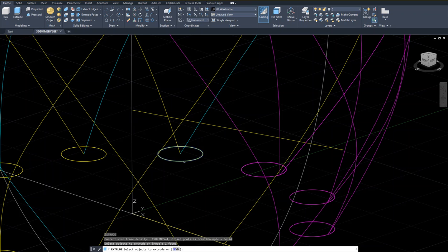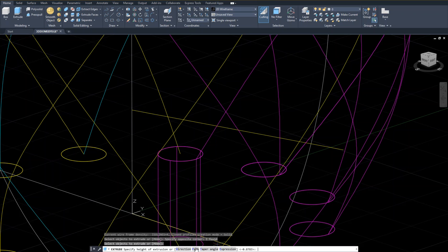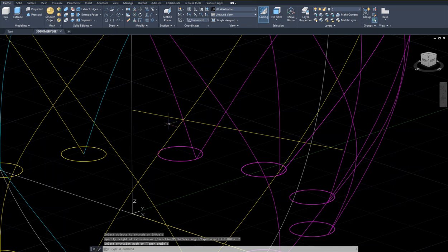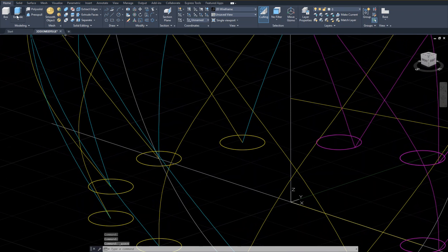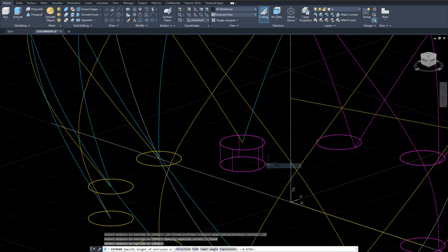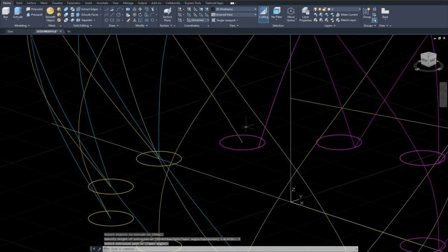Extrude is back. Now you hit enter key, enter, and then go over, select the path option. Okay. And perfect. Enter. And select the circle, enter, select the path option. Okay. Good. And Control S from time to time. Control S for save. We're going with the extrude option again. Okay. And select the circle, enter. Now we need to select the path option. Okay. Enter again. Extrude command comes back.